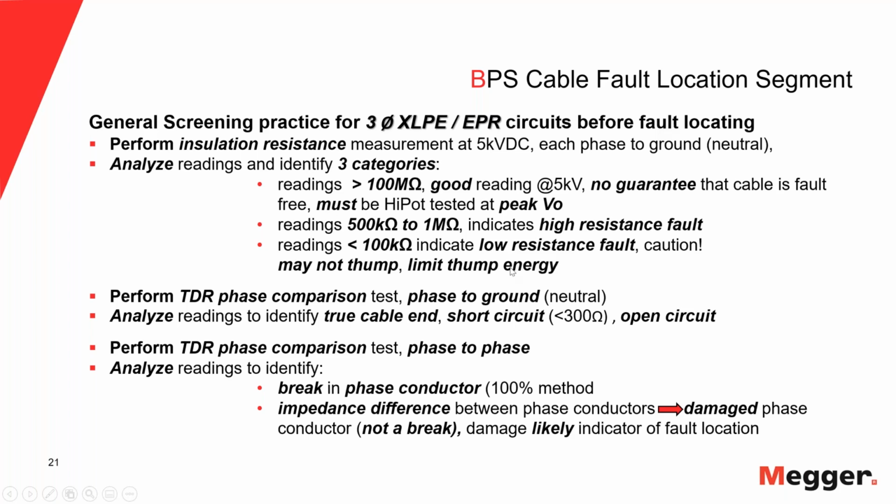Okay, so what I also can do is I can use the TDR, and you heard Marshall was saying the TDR is a distance meter, and that is what many people see as the benefit of a TDR, and that is certainly the case. But the TDR is in essence really not a distance meter by definition, it is an impedance meter. And it shows impedance, and it shows really impedance differences along a cable. A good cable would have no impedance change, so it's a flat line on your screen.